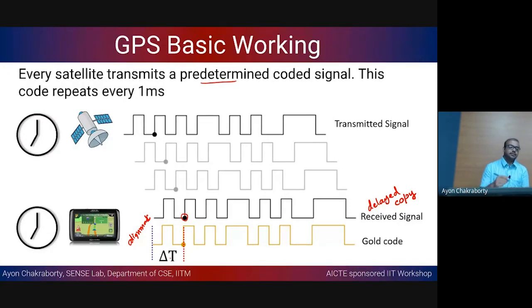or it can also give me the clock offset between these two devices, right? So if it is t equal to 1.5 here, at the same time what is going to be the time in this place, because I know the signal took delta t amount of time to fly. Okay, so when the signal reaches here, it ideally should be 1.5 plus delta t, right? So in that way you can also synchronize the clock of the receiver with respect to the transmitter's clock, in this case the satellite's clock.